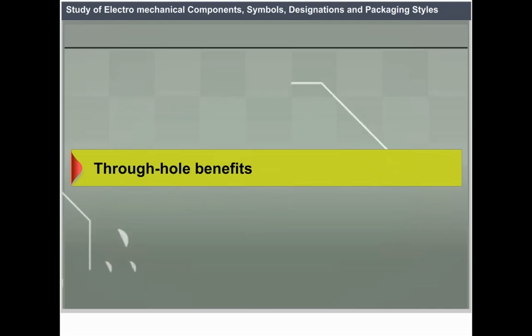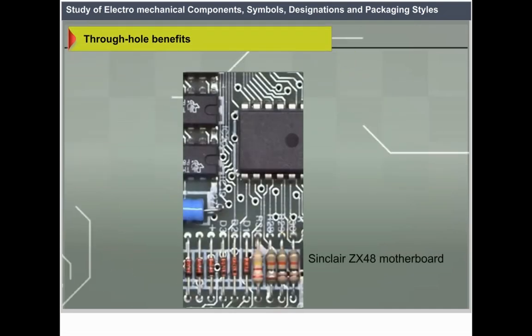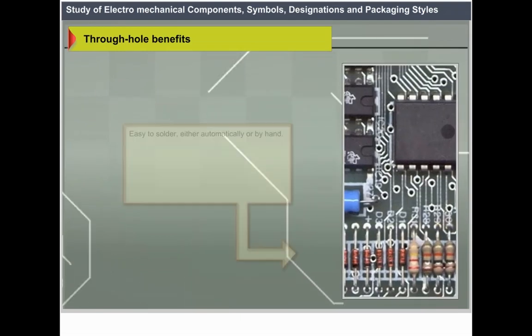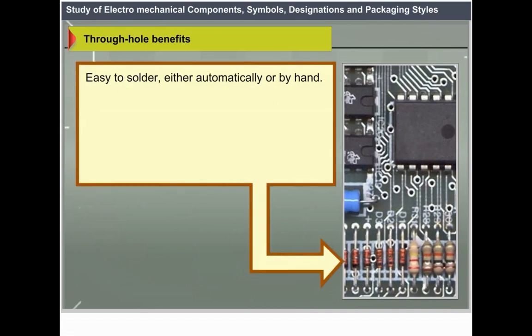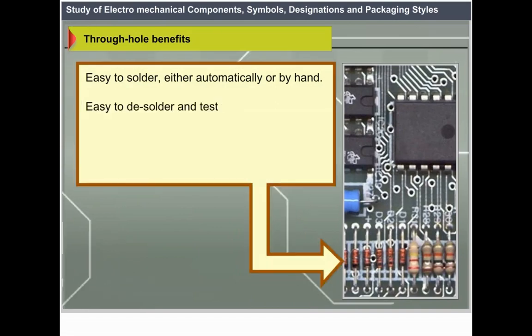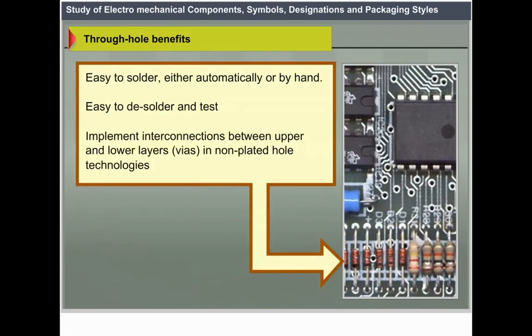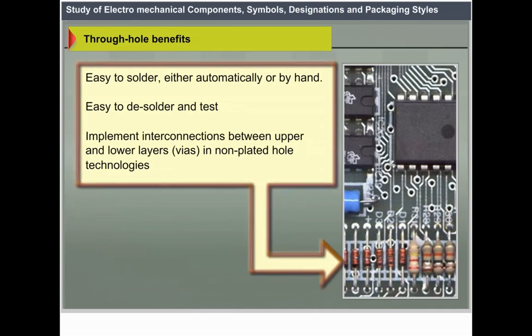Through-hole benefits. Sinclair ZX48 motherboard is shown in figure. Easy to solder either automatically or by hand. Easy to desolder and test. Implement interconnections between upper and lower layers, vias, in non-plated hole technologies.